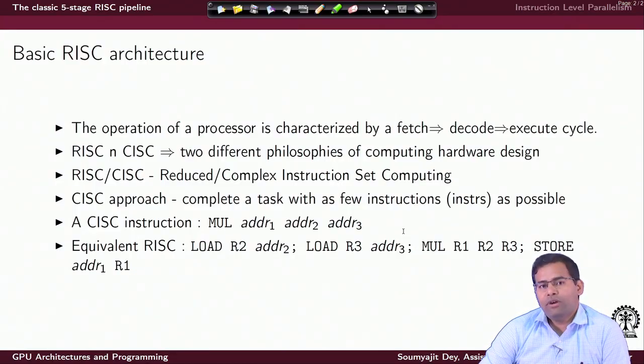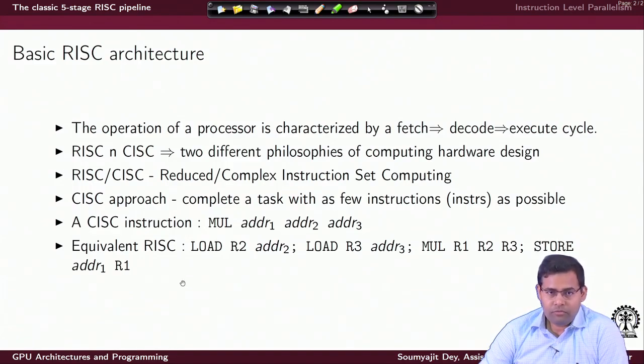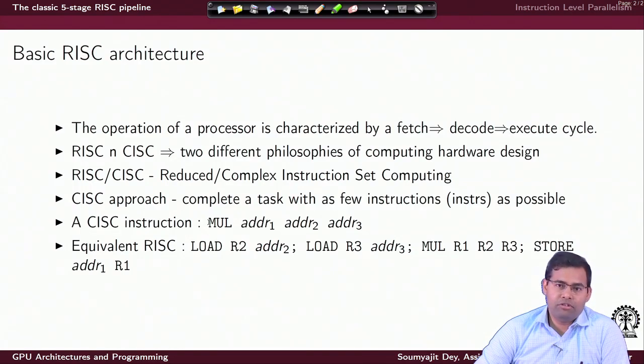Now, in terms of hardware design, that means we are thinking of a hardware which is complex enough to do all those things by executing a single instruction. The RISC philosophy is diametrically opposite to this. So, in an equivalent RISC world, we do not have this kind of a multiply instruction.